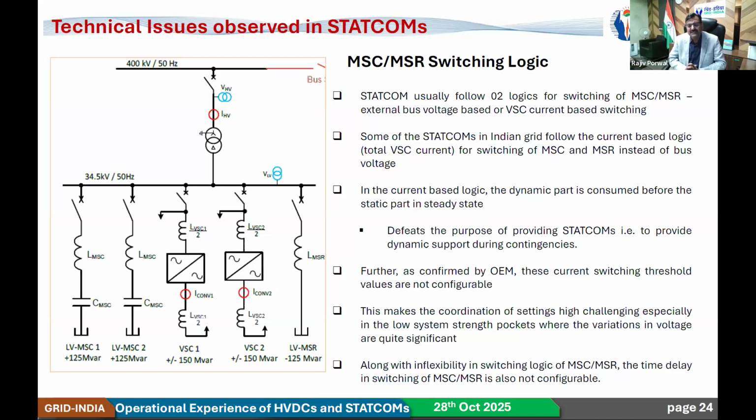And then it will take care of all the switching of MSC and MSR. What happens in some cases, if MSR is there, is that our dynamic support comes before any switching of MSR and MSC. The MSR and MSC switch only after a certain percentage of current is there in the VSC. Therefore, in all these cases, the dynamic portion comes before the static portion. So that is one issue.